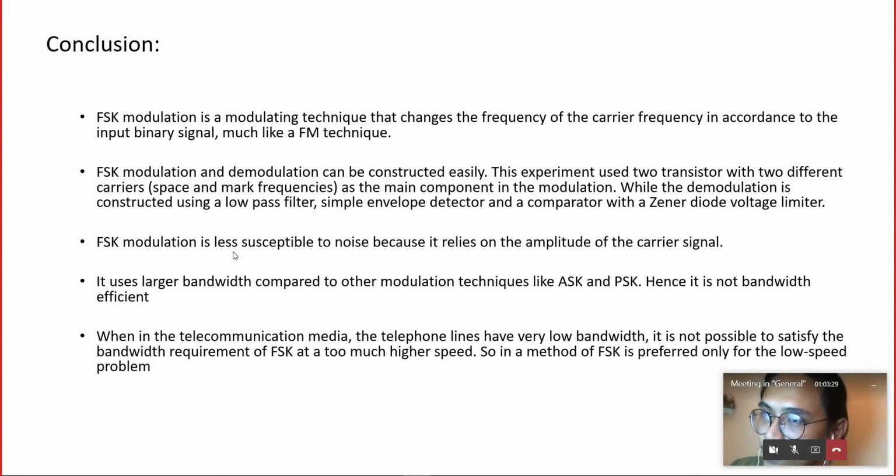And the FSK modulation is less susceptible to noise because it relies on the frequency rather than the amplitude of the carrier signal. And next, it uses a larger bandwidth compared to the other modulation techniques like ASK and PSK. Hence, it is not bandwidth efficient.